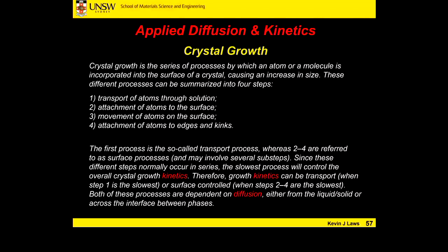Other things can actually speed it up. If your nucleus or site might be highly strained within the lattice, it might grow with defects in it, and then those defect sites could be sites for atoms to actually attach to much more quickly. And that would not then be a rate-defining step. That's a very, very fast step. All right? So there's many different steps within this growth process that can define our overall growth kinetics and the kinetics of our reaction. Great.